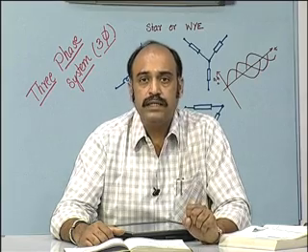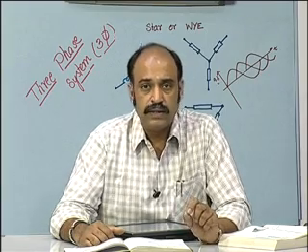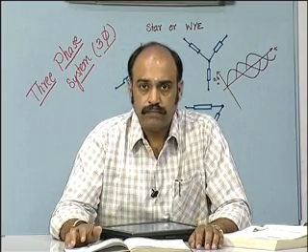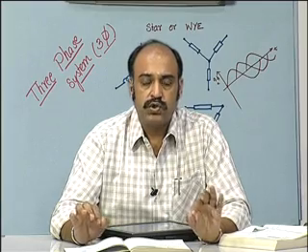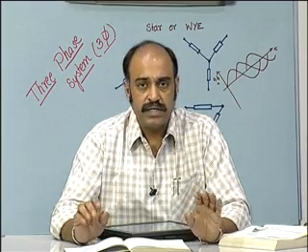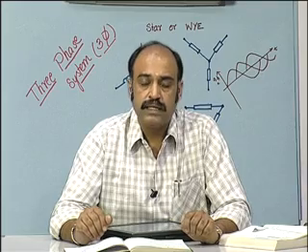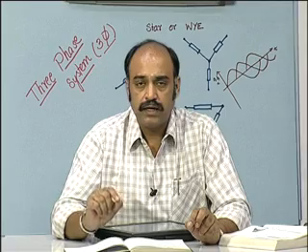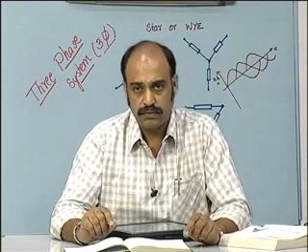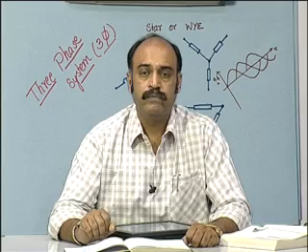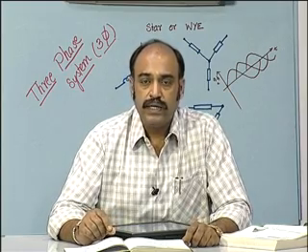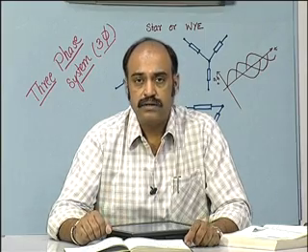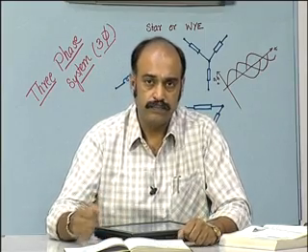The neutral point in the star circuit plays an important role in the sense that if the loads are balanced, the neutral points can be left floating, because under balanced load condition IA plus IB plus IC is equal to 0, which we discussed in the previous classes. Therefore, there is no need to connect the load neutral point to the neutral point of the source. There need not be a return path wire. As a consequence, we save copper, since you just need 3 wires to connect a 3-phase source to a 3-phase load.